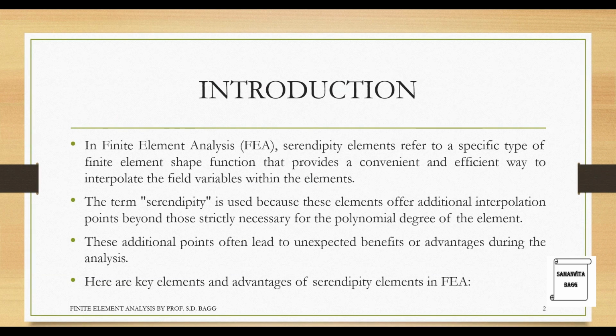In finite element analysis, serendipity elements refer to a specific type of finite element shape function that provides a convenient and efficient way to interpolate the field variables within the elements. The term serendipity is used because these elements offer additional interpolation points between those strictly necessary for the polynomial degree of the element. These additional points often lead to unexpected benefits or advantages during the analysis.